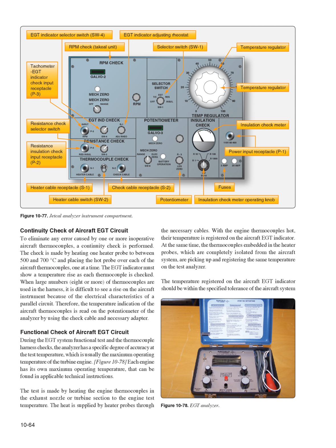When large numbers, 8 or more, of thermocouples are used in the harness, it is difficult to see a rise on the aircraft instrument because of the electrical characteristics of a parallel circuit. Therefore, the temperature indication of the aircraft thermocouples is read on the potentiometer of the analyzer by using the check cable and necessary adapter.